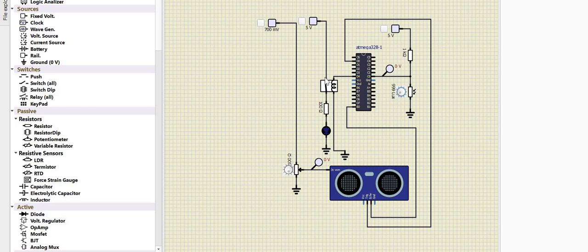So basically, here we have a relay as an actuator. This is the ultrasonic sensor, the relay is an actuator, and we have a bulb over here as an LED. When both the conditions that we have specified are met, for this the condition is it should be less than 150 centimeter, that is the range or the home space area that we have defined. And here the lux, that is the light intensity, the minimum it should be 150. That is, the daylight intensity should be 150.